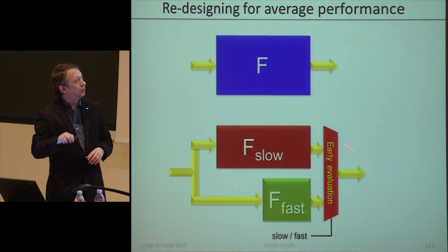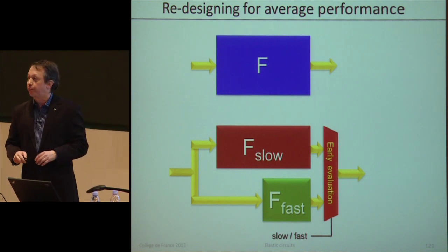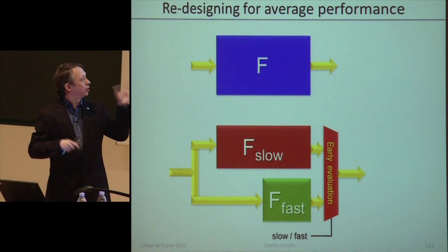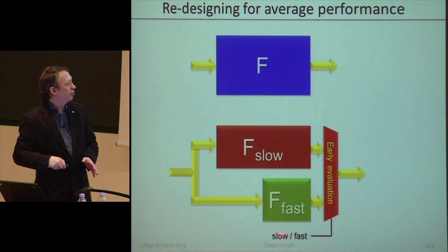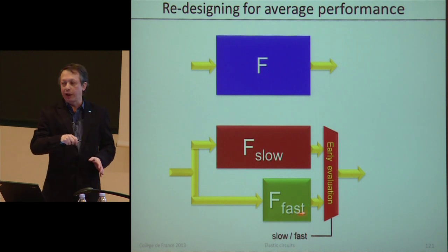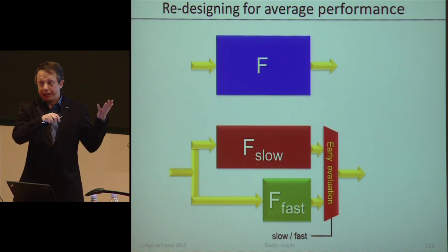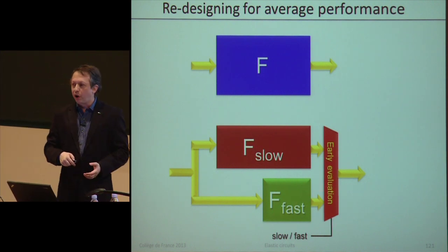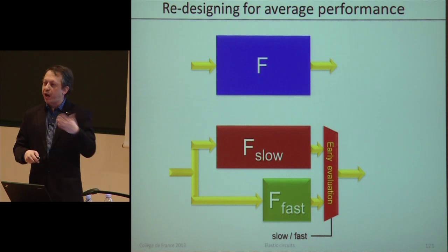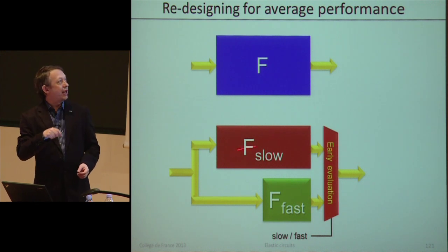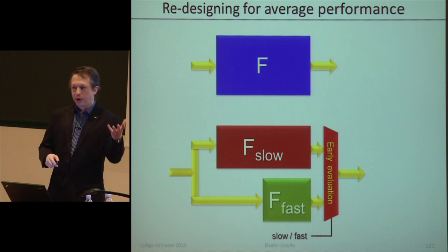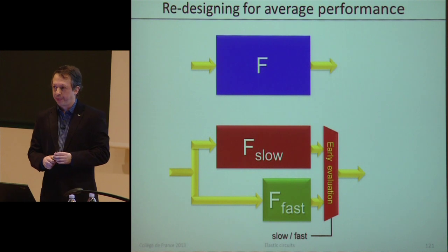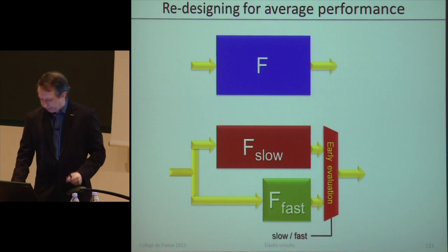Okay, so we can put this multiplexer with early evaluation, which basically means you make them run concurrently for the slow and fast case. If you know that this is a fast case, and this will take maybe one cycle, while this may take 3 elastic cycles, then you deliver the result. In case you use the fast option, then you will send an anti-token to the slow fragment of the function, and will cancel the other operation. Okay, in this way you can speed up.